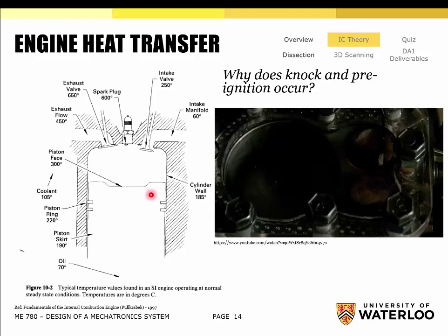it's going to get ignited and expanded, and then it's going to get exhausted. So during the combustion process, where's all the heat going? The next hottest thing, or I guess the very much hottest thing, is the exhaust valve. Okay, that's 650 degrees Celsius. The reason for that is all the combustion byproducts, all that high temperature gas, all that high enthalpy exhaust gas is going out the exhaust valve. And it's exposed directly to the combustion temperature, okay? And it has no evaporative cooling that the intake valve sees.